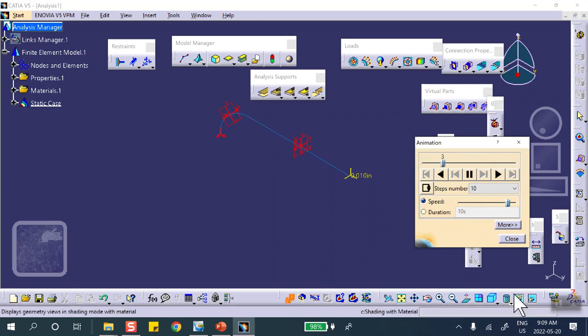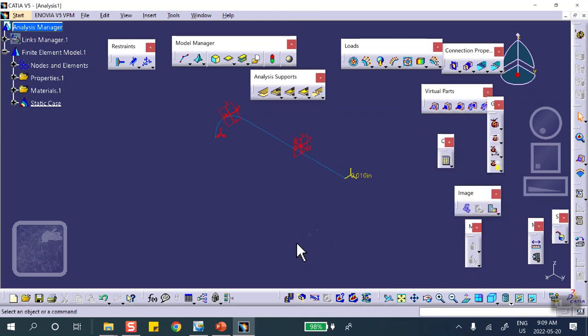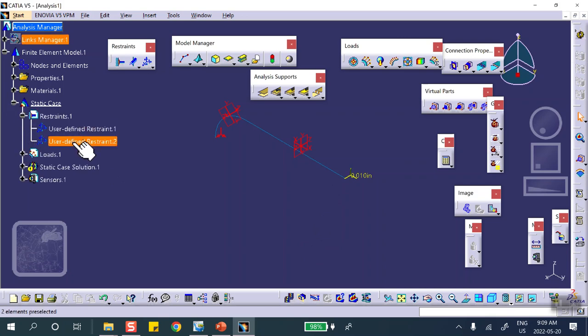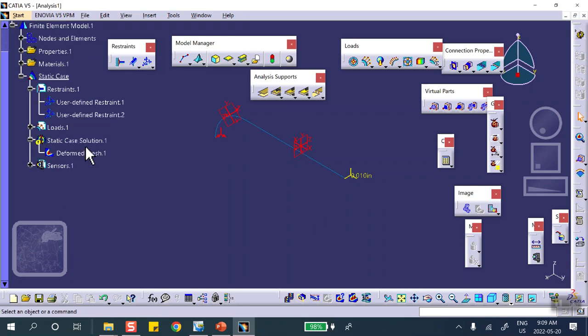So we're going to have to fix that, prevent that rigid body motion. There are other alternatives. You can probably take one point and say, don't come out of the plane. No displacement in the direction X, for example. As long as you can make it work, no problem. But the easiest way to do it is just that rotation 0. If you don't like that, go fix one point, not move in the X direction. I don't mean rotate, okay? Not move. Either way, so deactivate that. As a matter of fact, let me try it.